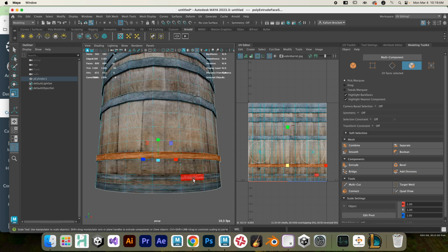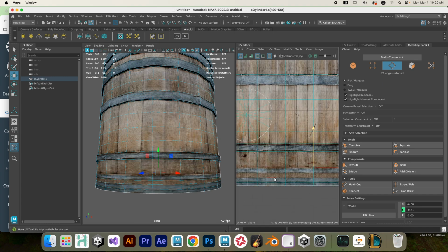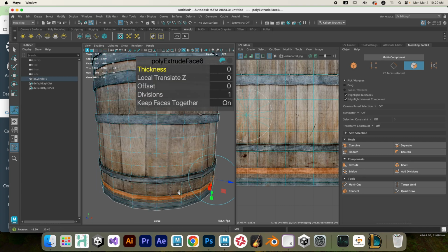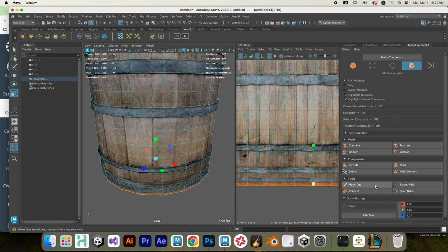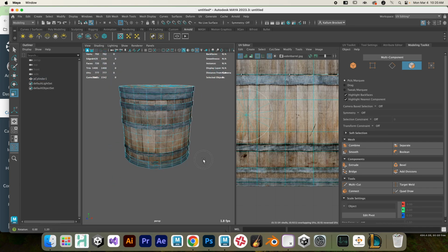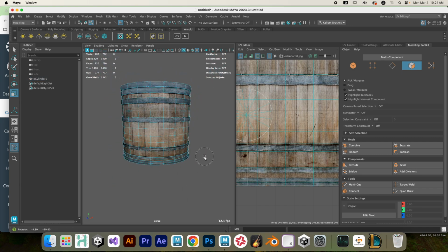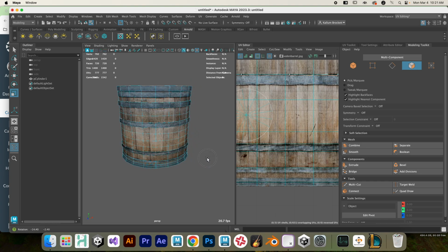All right, switch over to the bottom loops. Now, see, this one doesn't line up all the way. You can move it now, or you can move it later. Just trying to make sure I get this lined up. You can also, if you double click it here, that will change how it applies on the mesh. There we go. All right, so then face select, shift, double click, extrude, scale. Bring it out. Shift, double click, extrude, scale. And then finally shift. Nope, missed. That's a tight one. Shift, double click, extrude, scale. There we go. All right. So there is the outside loop of my barrel.